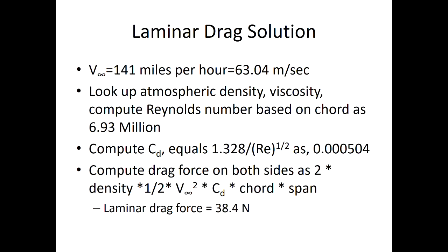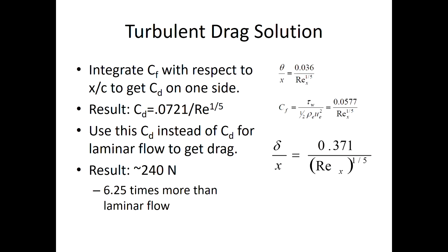We try to keep laminar airfoils, postpone the transition. One of the ways we said is to make the skin as smooth as possible, no roughness. Also avoid adverse pressure gradient as far as possible to remove the inflection point.